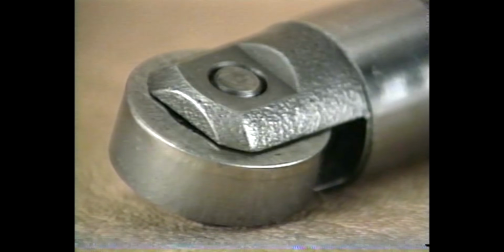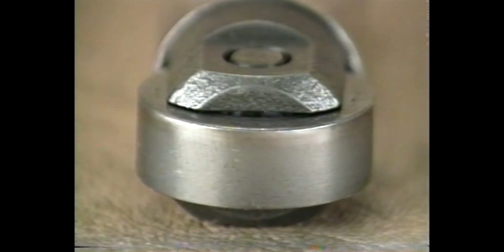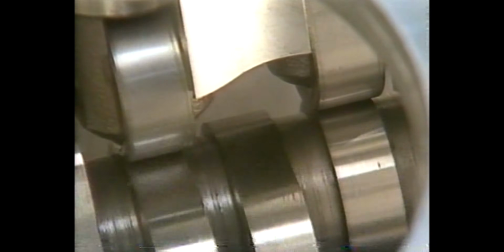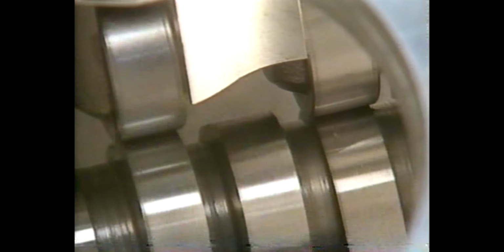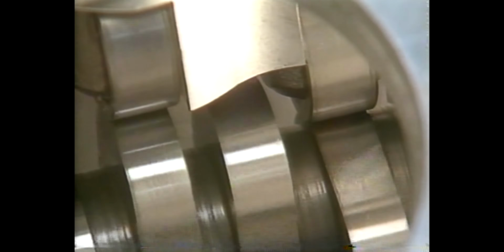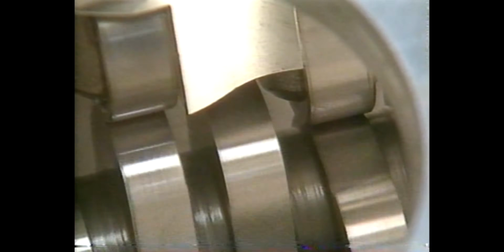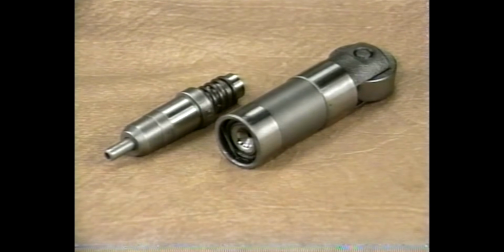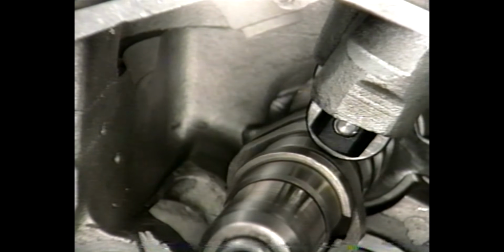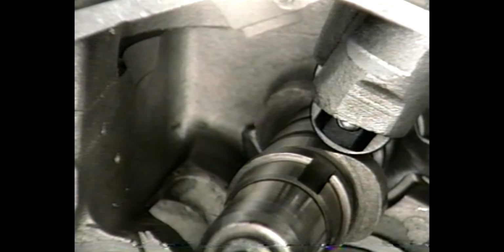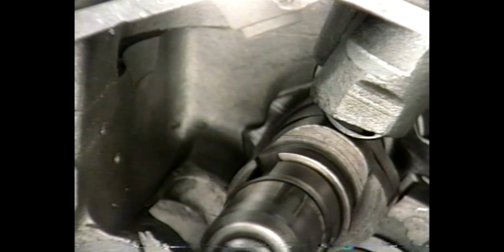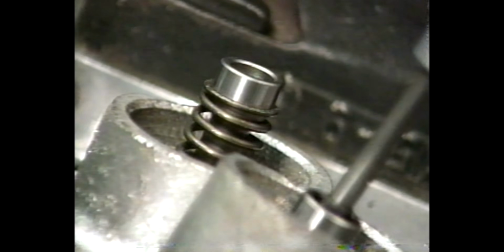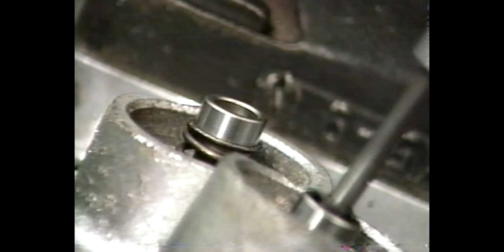Hydraulic lifters have a needle bearing roller which enables them to maintain contact with cam lobes that have extremely aggressive ramps. Hydraulic lifters rely solely on oil pressure to maintain a zero valve backlash clearance, even when the cylinders expand with heat. Use of these lifters produces a relatively noise-free operation. The downside feature of hydraulic lifters is the very fact that they rely on oil pressure for proper operation. This means that they are also very susceptible to any fluctuations in oil pressure in our engine.